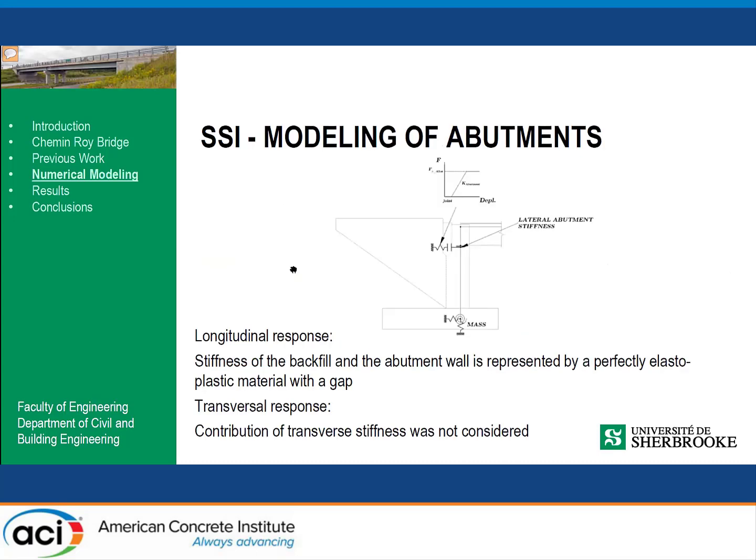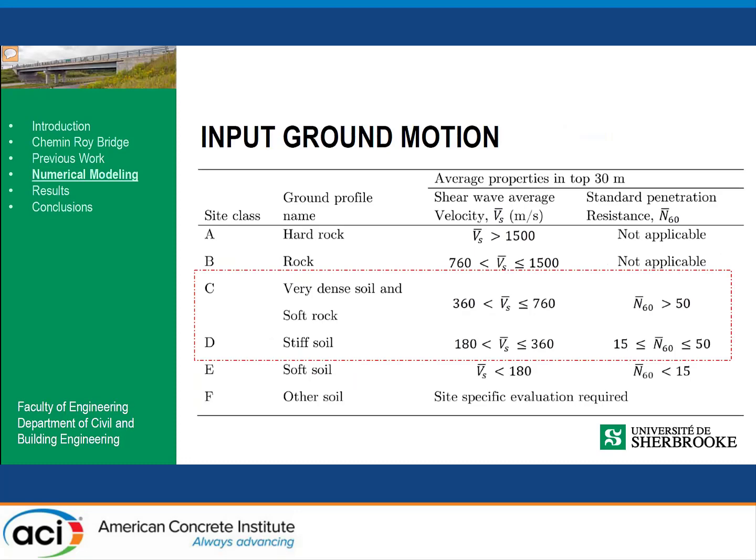For the abutment, the stiffness of the backfill and the abutment wall is represented with an elastoplastic material with a gap, in the longitudinal response. The contribution of the transverse stiffness was not considered, as is recommended in Caltrans and other guidelines.